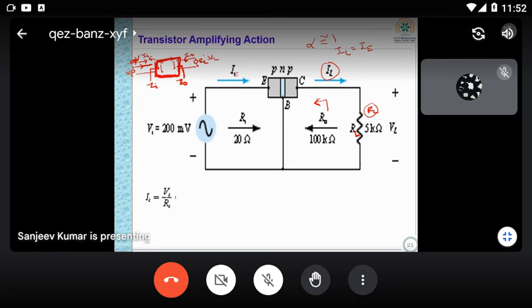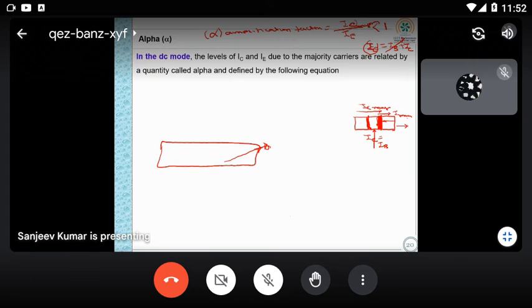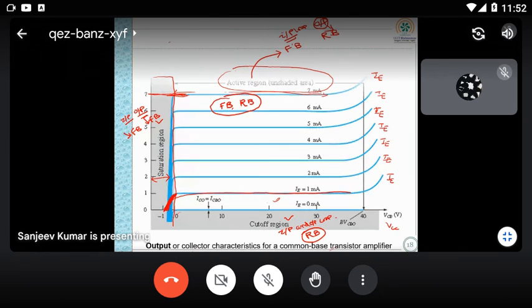You have seen this previous diagram also, which you will calculate here. Now, how to calculate the output impedance? Output resistance or impedance is the change in voltage by change in current. Change in voltage means this is your VCC you are giving. For example, I am taking one change in voltage, this line. So I have to take a tangential line or two difference points.